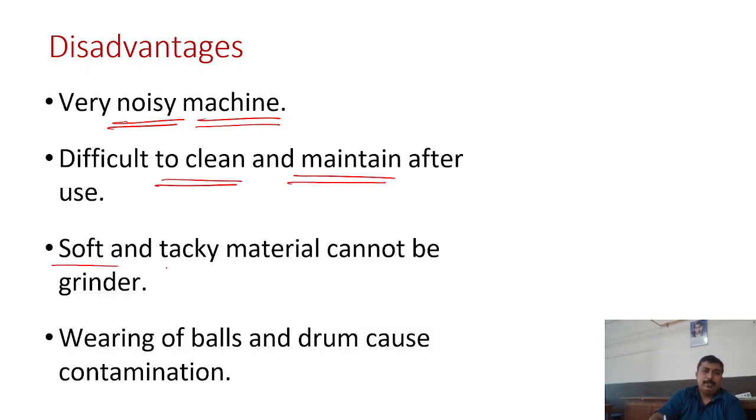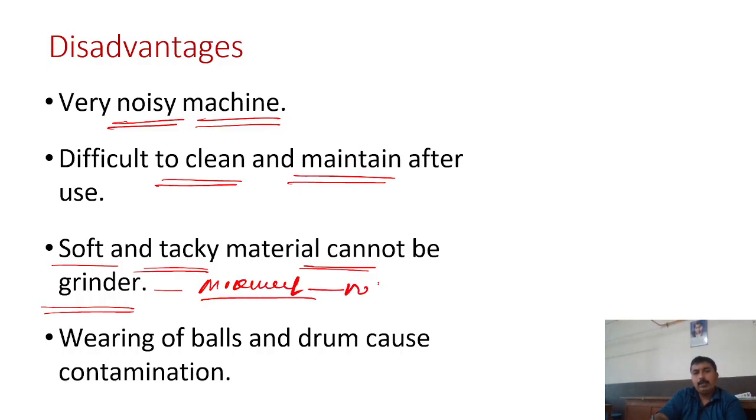Soft and tacky material, sticky material, cannot be ground because that may hinder the movement of balls. So if you are using sticky material, the movement of balls will not take place, because sticky material helps in the sticking or adhesion of the balls on the inner walls of the drum, and that's why you cannot grind sticky material.